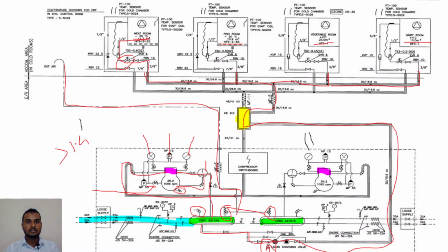I forgot to say, this is the fan, the cooling fan. These are cooling fans which are used as the second cooling medium. Okay. Then when the evaporator is cooling down, the thermostatic expansion valve shuts off the solenoid valve. Then the refrigerant will return through this line, and it comes through the thermal exchanger. Then it goes to the compressor suction.